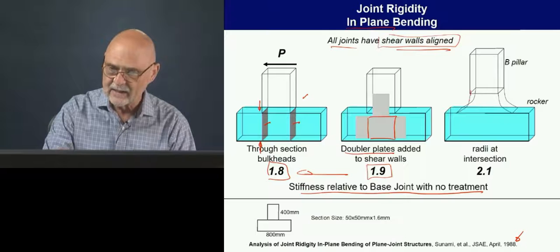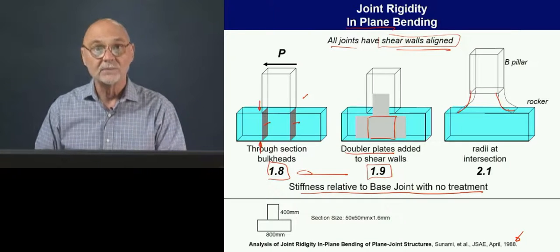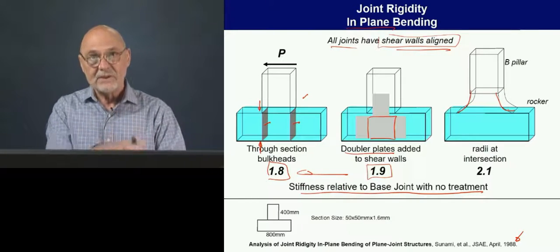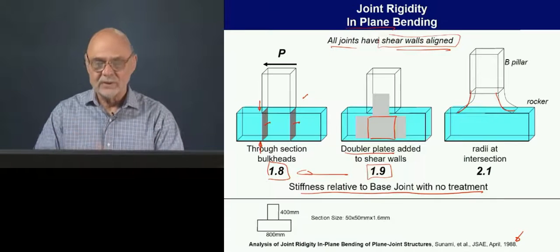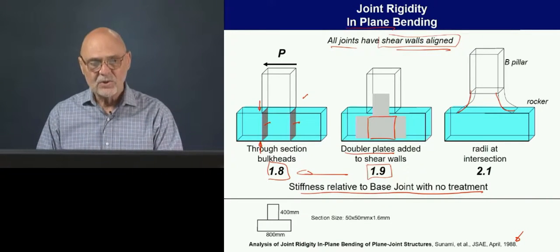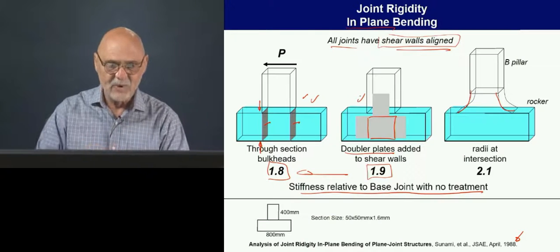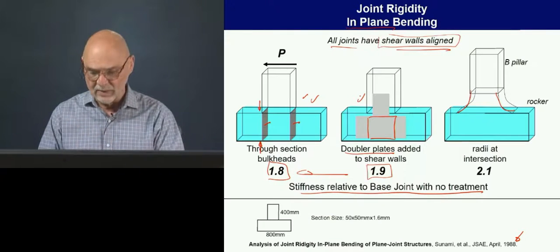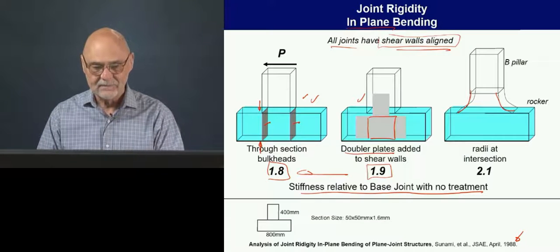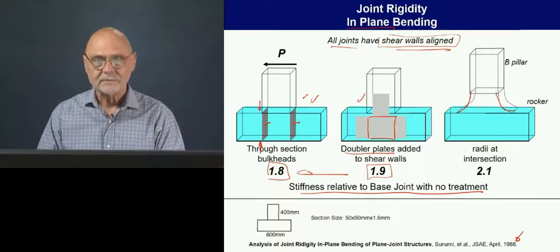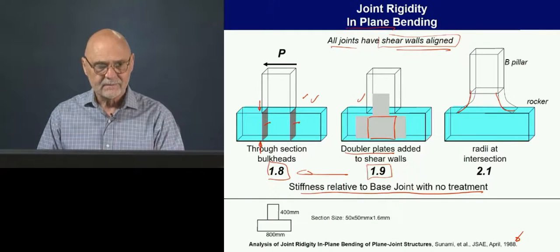And then here is adding the radii alone. So each one of these elements by itself essentially will double the rigidity. Okay, so these are different ways to do it. These two add more mass than just an intelligent placement of beads. Okay, so let's try to quantify this and see how good we can really get.